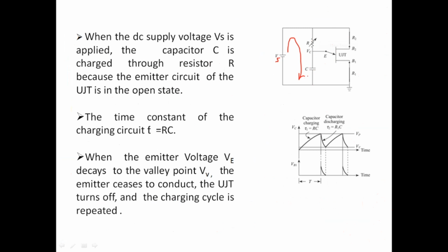How long will the capacitor charge? It will charge until the voltage across the capacitor reaches the value VP, the peak voltage. As I showed previously, once the voltage applied to the emitter is equal to VP, more and more carriers are injected into the lower layer, and this resistance will come down to very small, like 50 ohms.